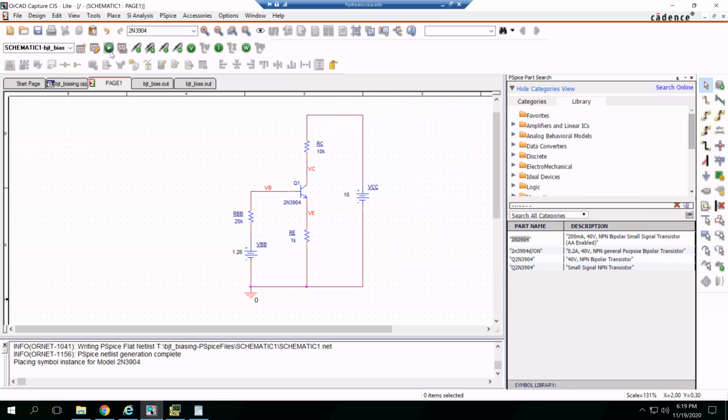Then I'm just going to go ahead and select the voltage and the current. You can see I already ran the simulation, and I got my current right about where it's supposed to be. It's close enough. That's another thing too, as you're doing this: if it asks you for half a milliamp, 500 microamps, you don't have to get it perfectly right at 500. If you're at 495 or 505, you're pretty close. It's close enough within a margin of error. So I ran the simulation.